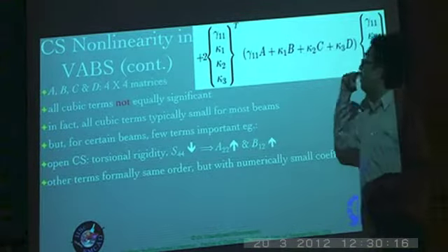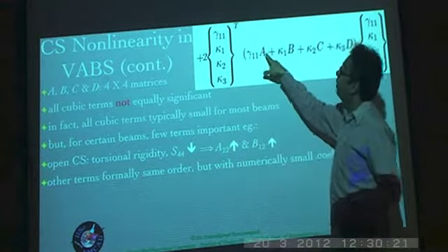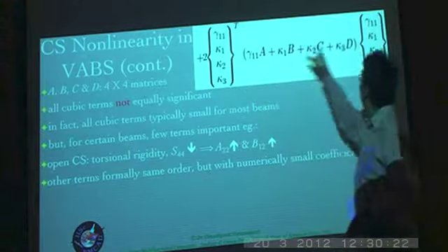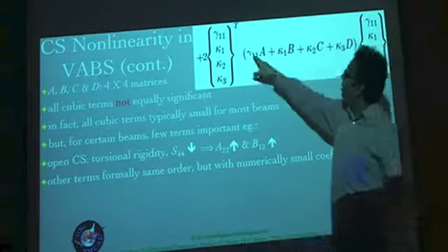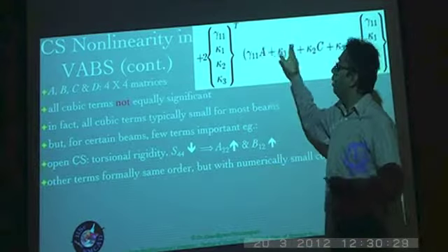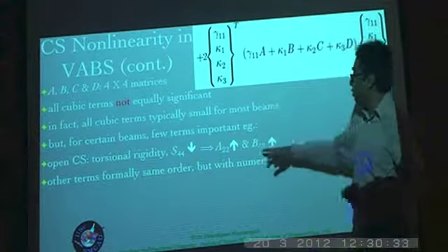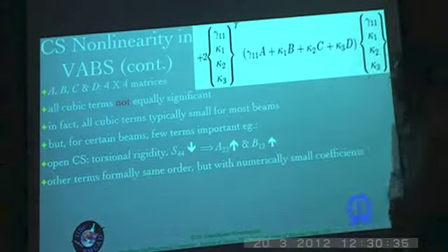I mentioned only A12 and B12, but you see that A22 is also a term which involves kappa 1 squared along with gamma 11. So it's once again an extension twist coupling. So not only A12 and B12, but even A22, for example, can contribute to an extension twist coupling. So that's basically what is mentioned over there.